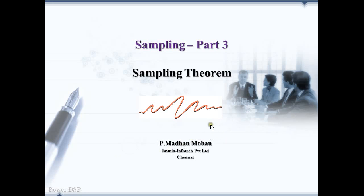In the first part, we have seen what is the signal ambiguity that is present in the frequency domain, which mandates the sampling theorem. And in the second part, we have seen why the spectrum is repeating, which shows what is the maximum frequency component in the input signal that we can represent in the spectrum without any problem.